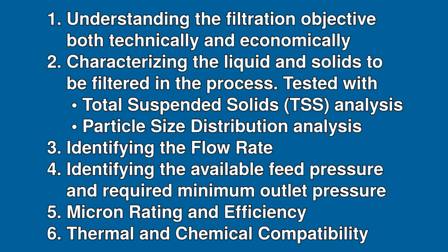Understood. Thank you for going into depth about that. In summary, selecting a liquid filtration design includes understanding the filtration objective both technically and economically, characterizing the liquid and solids to be filtered in the process, identifying the flow rate, identifying the available feed pressure and required minimum outlet pressure, micron rating and efficiency, and thermal and chemical compatibility.